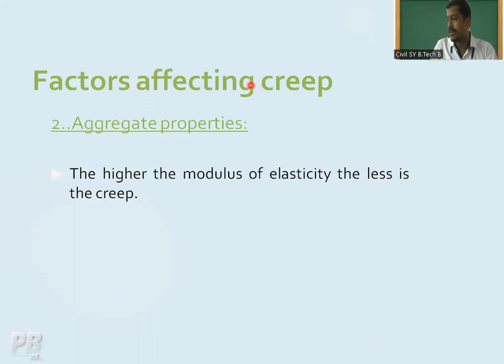In case of steel, we are discussing. In case of your concrete, you are having that formula. Static modulus of elasticity Ec equals 5000 under root of fck. Yesterday only we have discussed that particular formula.